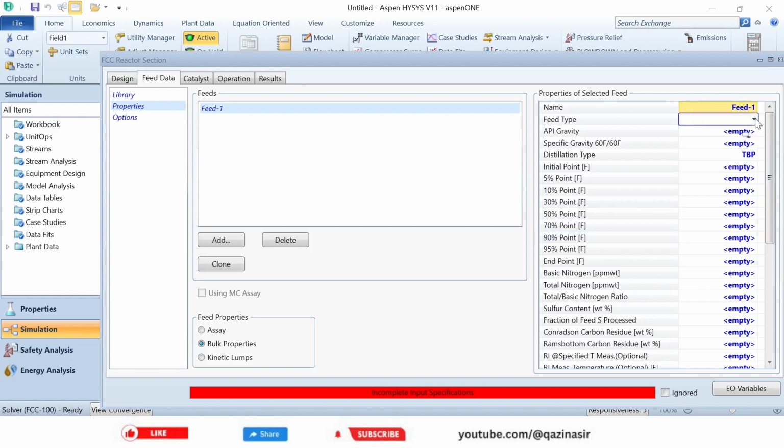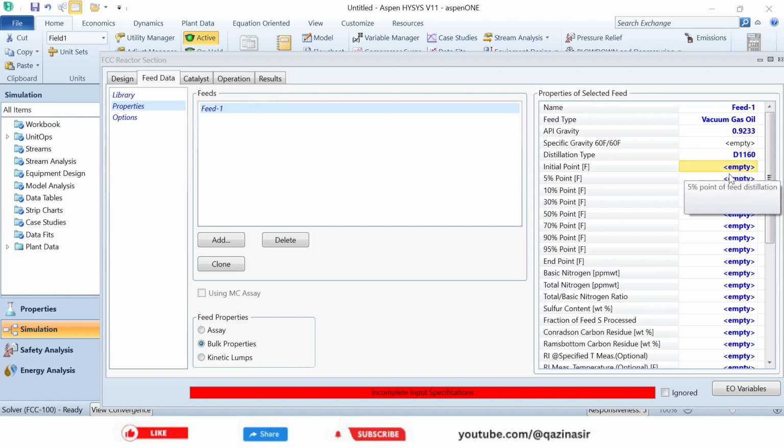So the first thing is the feed type, vacuum gas oil. The specific gravity that we are using is 0.9233. The distillation type is D1160. The initial point temperature in Fahrenheit is 503.6.